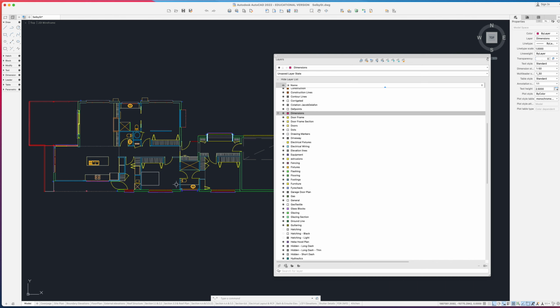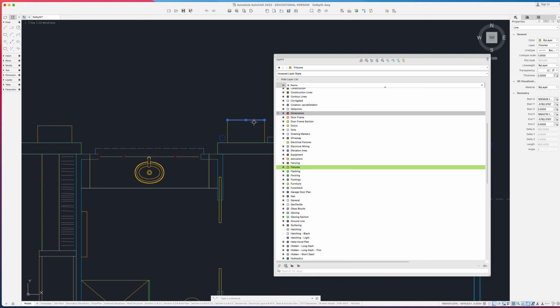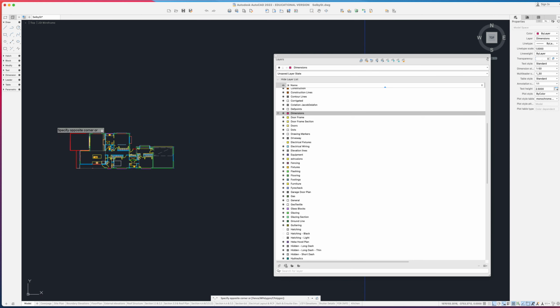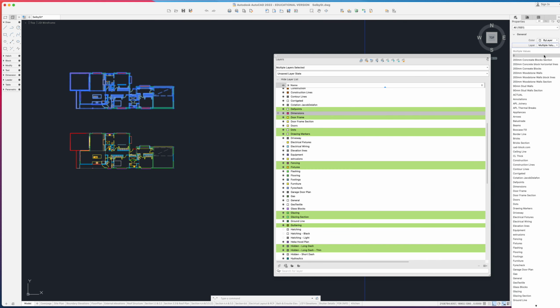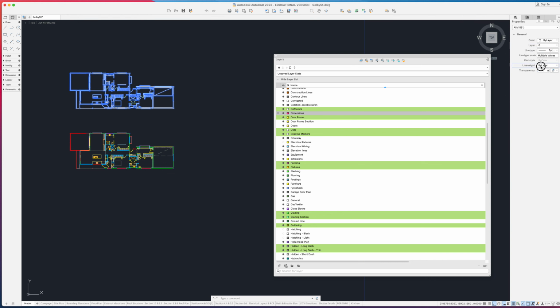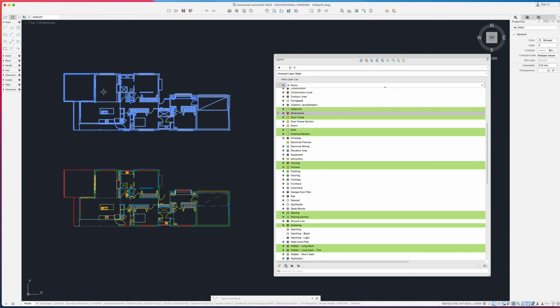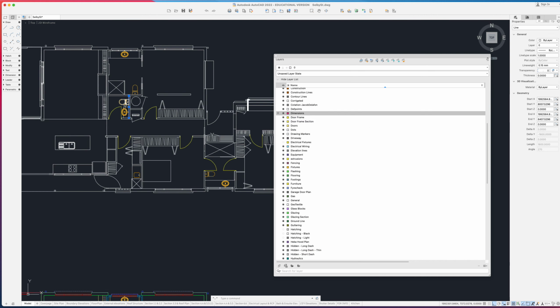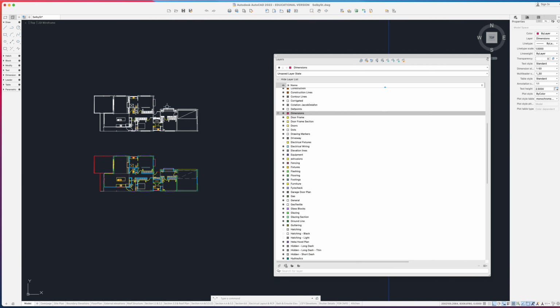Okay, so I've got my doors sitting in here. This is looking pretty good. Any kind of extra information around the outside, I'm going to delete. Remember, this is a copy. And then I always, once I've tidied it up, I'm going to make a second copy. Select this guy. I'm going to put all of him into layer 0. And my line weight, I'm going to put all the way down to 0.15, just so that I can see what it's like without those line types in there as well, or different line weights.